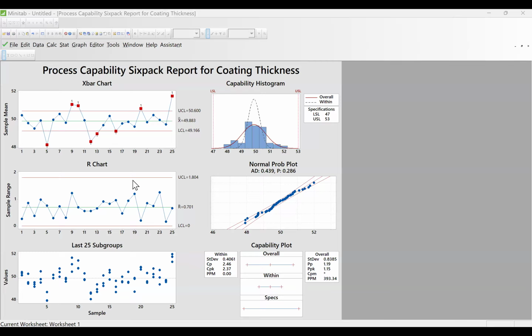And the definition of short term and long term, we have to write down after knowing the product, the characteristics, the customer demand, and all the facts presented to you. Then we can write a definition of what is short term and what is long term. So the ultimate goal is that your CP/CPK and PP/PPK must be close to each other, so that you can use the process for short-term application as well as long-term application.